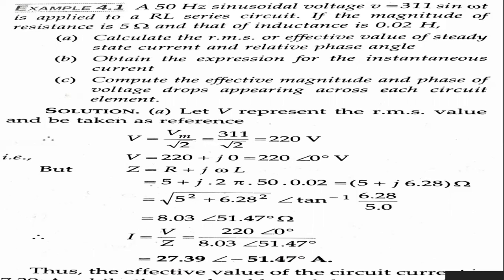If you have either one, you need to consider that X will be equal to XL if inductor is there, and if capacitor is there, X is treated as XC. If both are there, you need to consider the difference of XL and XC, depending on which is greater and which is lesser. Already we have simplified many numericals on that. So I is equal to V by Z will be the case. Now come to the point of the unknown parameter, here that is Z. How can I calculate my Z?